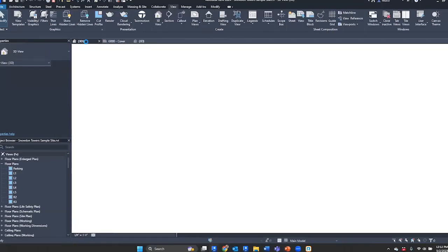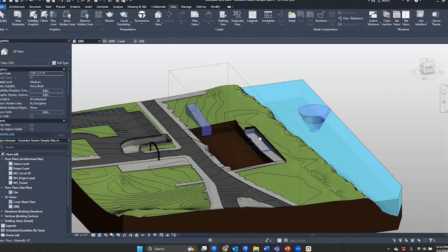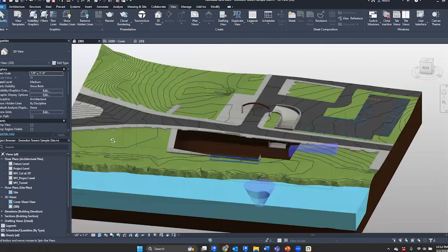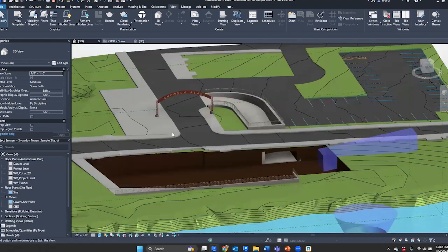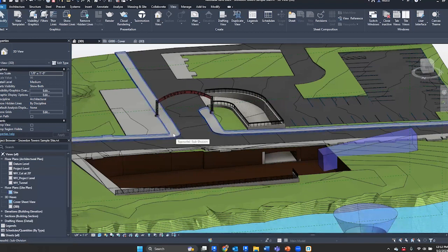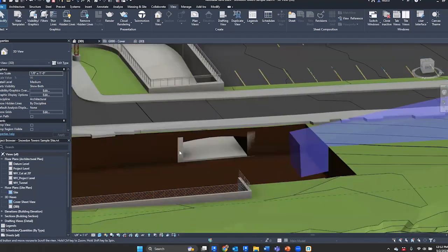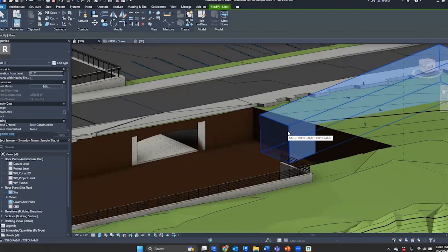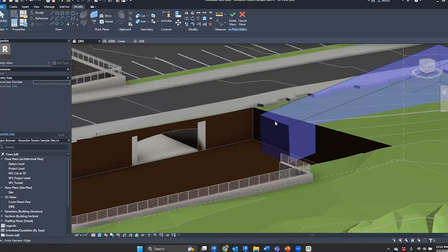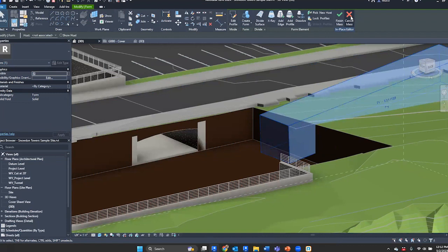So here's the site model that I've worked with this project. This again comes with the samples that you will have preloaded when you install 2024. So let's take a look. There are the subdivisions. There are the voids, and I created an initial void over here. There's no more pads. So in order to cut a surface, cut a solid, TopoSolid, you'll create a mass. And this is a solid mass, as you can see here in my mass properties. I grab the mass, I edit in place, and you could see that this element that I created is a solid. Okay, so cancel the mass.